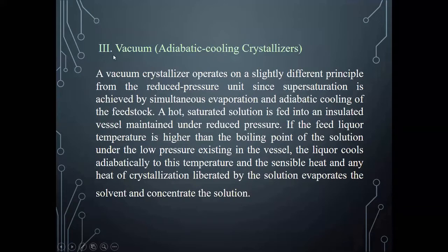So in the third type, we have adiabatic operation, so no heat is liberated from the system. The crystallization process is operated under vacuum, so you are able to reduce the amount of solvent present in the feed and at the same time cool it simultaneously.